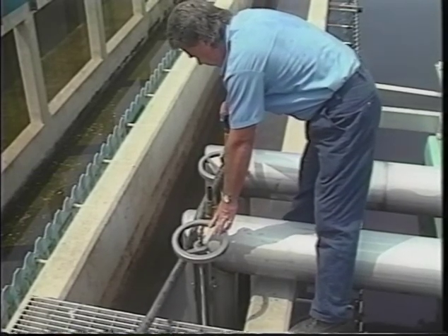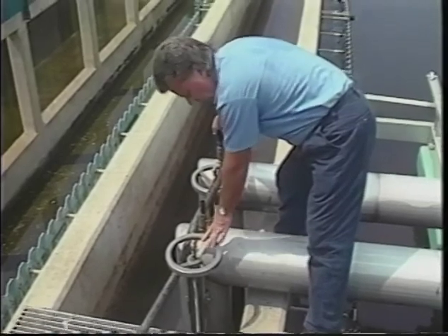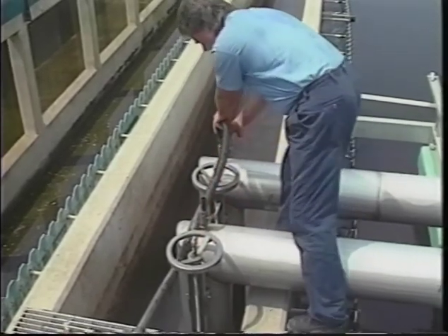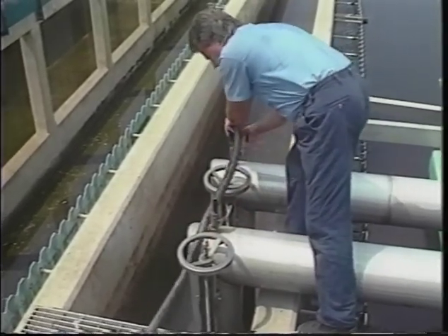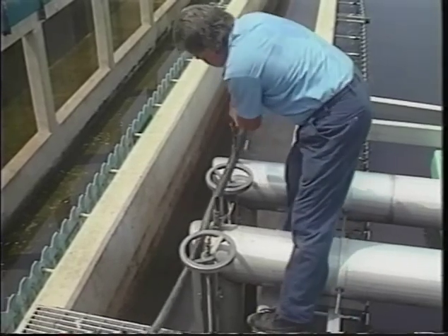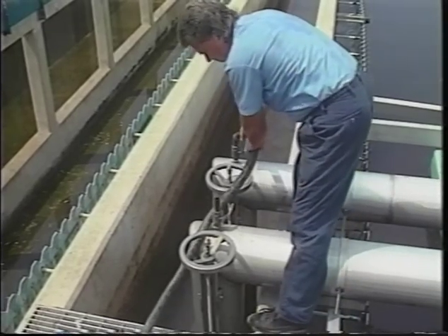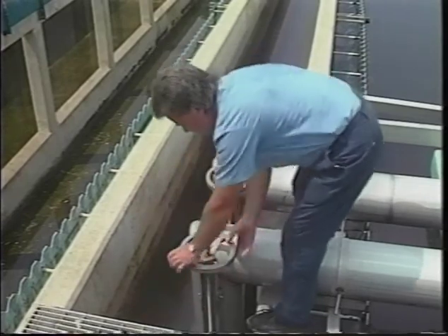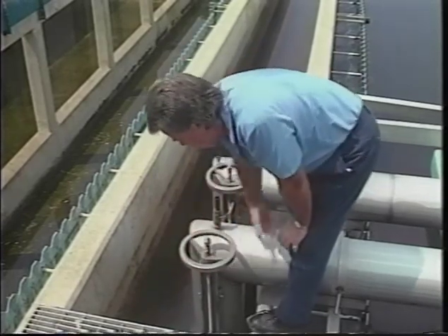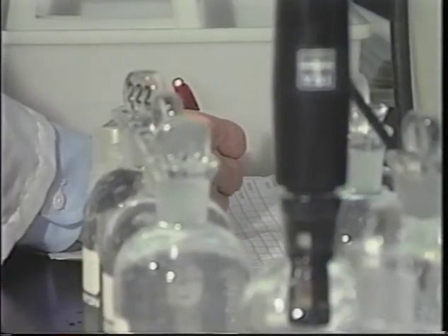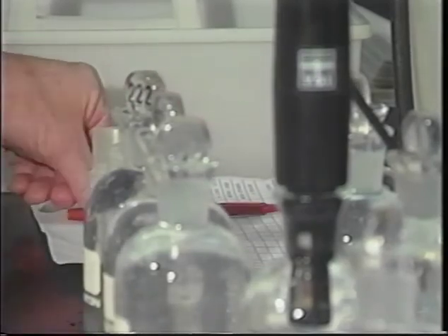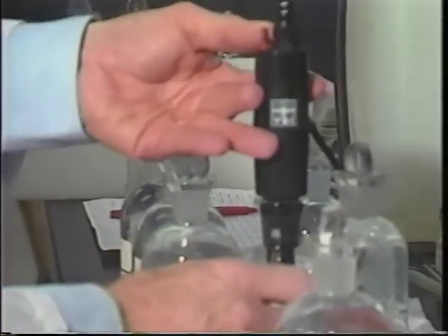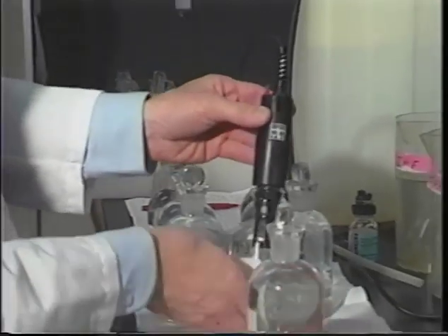It is essential for the operator to carefully control the amount of activated sludge returned and wasted from the clarifier. The amount of activated sludge returned or wasted is dependent on hydraulic and organic loading to the system. Only through proper process control testing and monitoring can the operator make the proper decisions and adjustments.